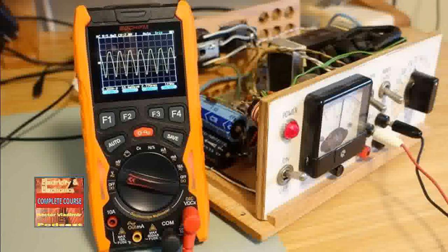AC meter readings. When AC is applied to the meter movement, the needle does not deflect. Remember that AC rapidly changes direction. The meter coil current changes direction in pace with the applied AC voltage. The result is that the magnetic field rises and collapses, and then reverses so rapidly that the coil cannot deflect the needle. The coil simply vibrates under the influence of applied AC voltage.